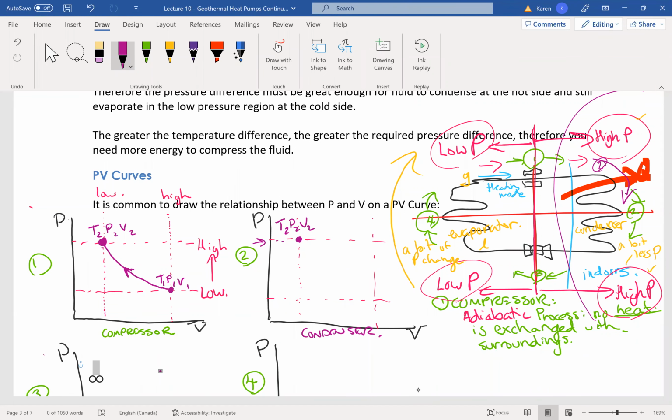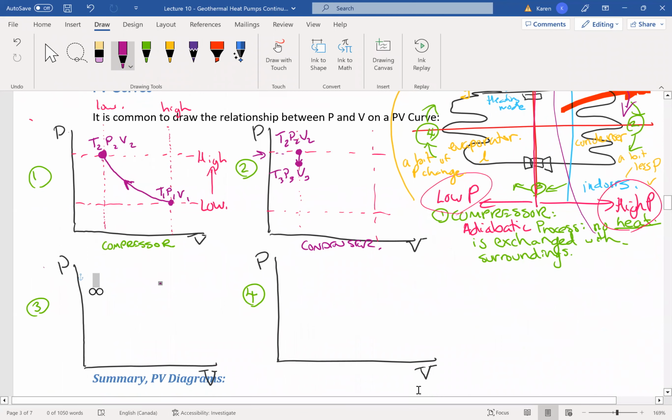And then I'm going to hold volume constant. So as you said, it has to stay in the same vertical, because it's a constant volume, but the pressure is going to relieve just a little bit because some of those gas molecules are going away. So right here, I would say that this is the temperature, pressure, and volume of point 3. Point 3 is going into that expansion valve.